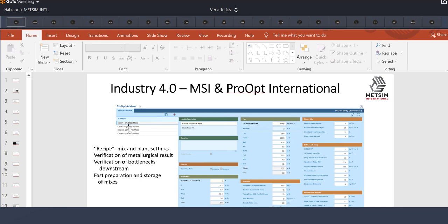And what we can see here is we're quickly able to do 4 cases that I've got shown here. No black mass, 10%, 20%, 30%. So I can actually just change a number, tell it to execute, save the results. Change a number, run it, view the results. And then at the end, what I have are several simulations that have been run with all of the outputs. And I can say, this is the recipe that we need. This is how we're going to operate this plant. And we were able to do that without actually going out into the plant and having to run those things.